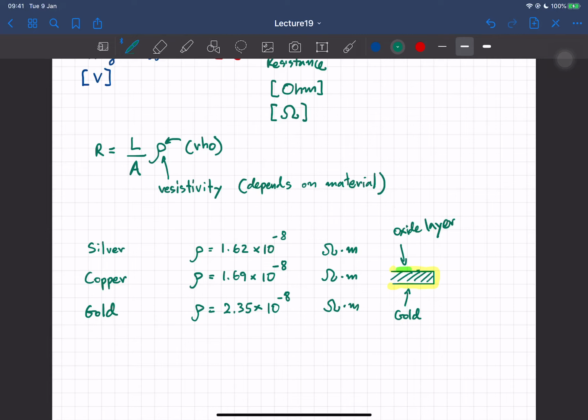Okay, so it's not going to do anything to the material, but it's going to form a kind of protective layer around the material, which is not what we want. So that's the issue here. Well, gold is expensive, of course. So in some cases, you can also get the same thing by not plating gold, but plating some other material which also doesn't form an oxide layer, like nickel. So sometimes you have a nickel plated connector, and it's doing the same thing here.